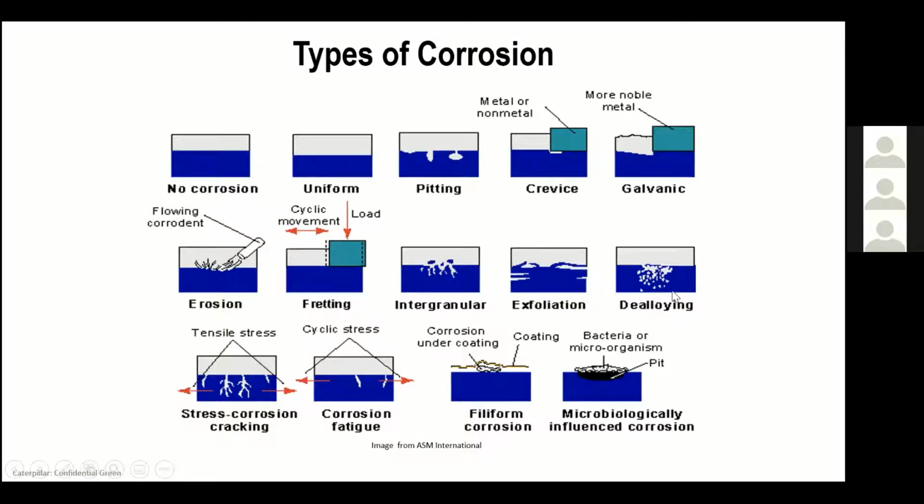Usually when it gets to this point and when they get involved, it's a type of corrosion that's really detrimental. So things that fail, like bridges or certain types of components on equipment or machines like automobiles. So that's when corrosion gets really bad, or you have certain types of fatigue. I'm not going to cover that a whole lot, but I wanted to mention it so you can see the complexity when we talk about different types of corrosion. And then I'll probably show something that is a combination, because a lot of times there's a number of things that are occurring. I think I have one slide here from what we do in our organization, showing a combination of high chlorides and microbiologically influenced corrosion.